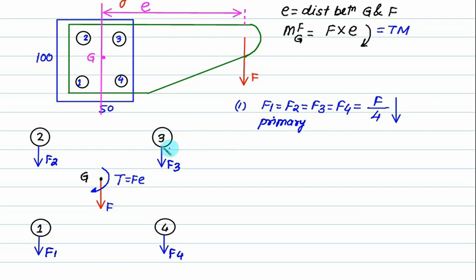Here, the rivet will be cut in this plane, and this plane is a circular section. So this force is parallel to the circular section. That is why it is called the primary shear force. Now to balance this torque, the procedure involved is to join with G like this. So join all the rivet centers with the given point, and on each rivet center we have to show one force, either this one or this one, which is perpendicular to the line of action.